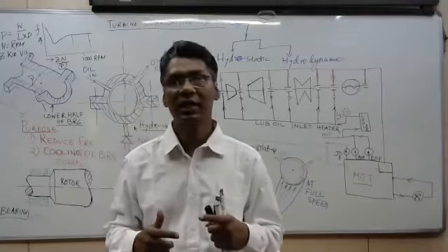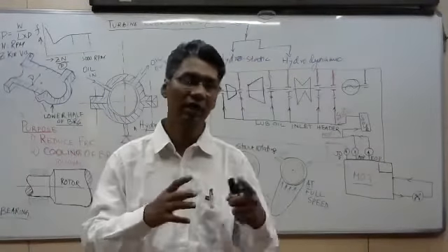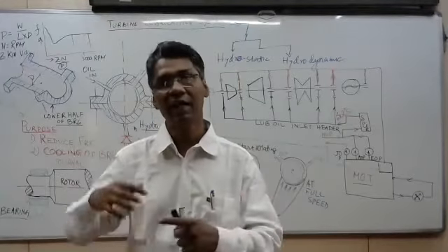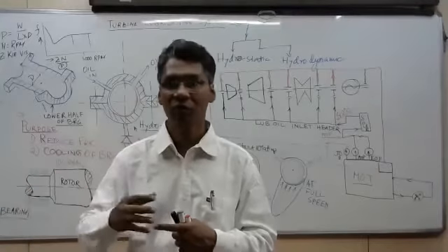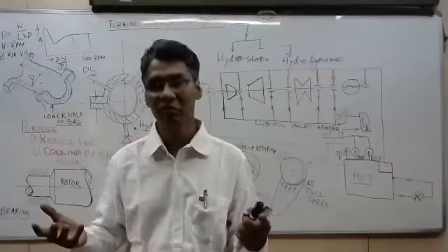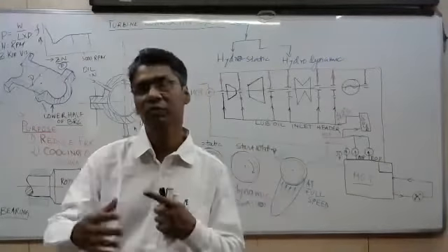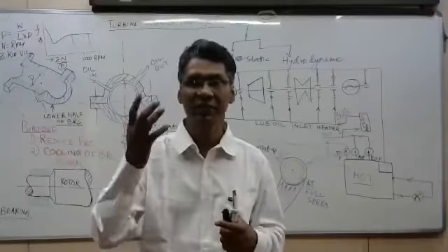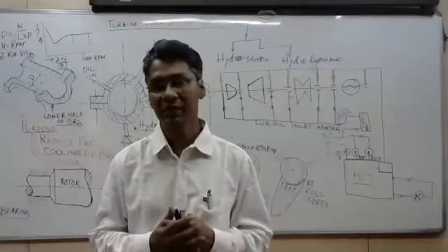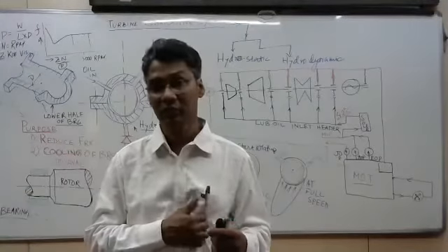So, because it is running at a higher speed of 3000 rpm, it is achievable. Roller and other bearings can do their function at lower rpm as well as higher rpm. At higher rpm, higher friction; at lower rpm, lower friction. But in a journal bearing it is different. At lower rpm, the bearing properties don't develop. They develop with speed. As it increases its speed, it has some mechanism by which it will develop its bearing properties, which I'll let you know about. So that's why the journal bearing is used.